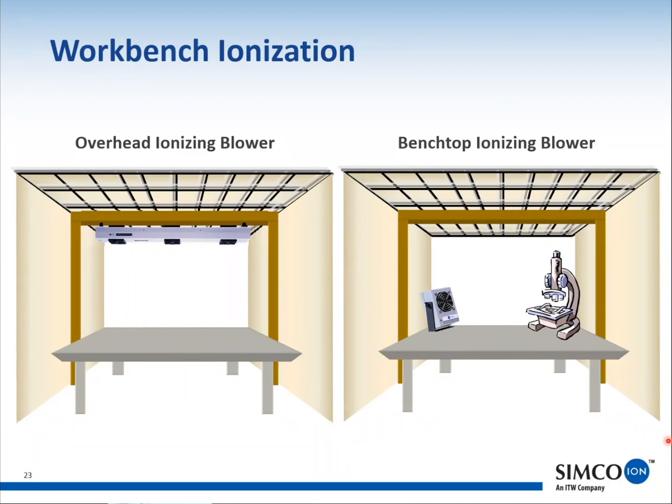A lot of times these Tyvek sheets, when they're getting placed on the trays, they go through a variety of rollers. And I've had people want to ionize the beginning of that. And I'm going, yeah, but as soon as it goes around that roller, it's going to recharge. So you've got to add more ionization. So ideally you want to ionize it right before you put it on your product. So you advise that I may put some ionization points across the machine. Correct. Yeah, you need them in various locations in most situations.